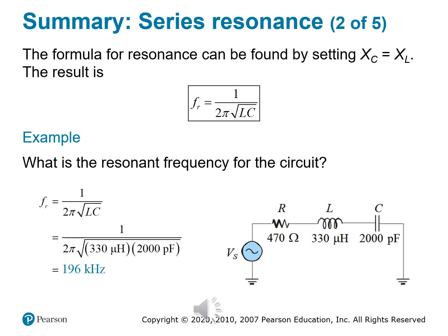Resonance revealed, slide 2 of 5. Action. So, welcome back, Resonance fans. In our last segment, we talked about the magical moment when X_L is equal to X_C, and the classic highlight of the movie when Neo and Agent Smith actually cancel each other out, or when at least Neo realizes what has to be done. Right. So, the condition for resonance in a series RLC circuit means that X_L has to equal X_C, but in opposite polarities. So let's just go ahead and do some math, right?